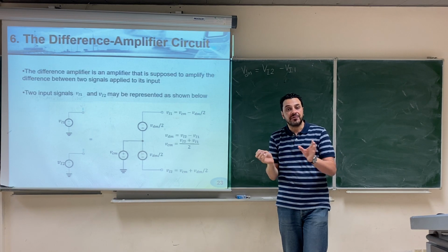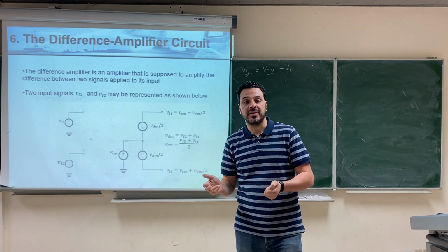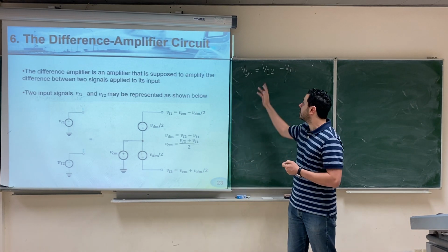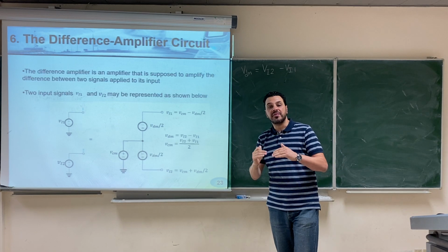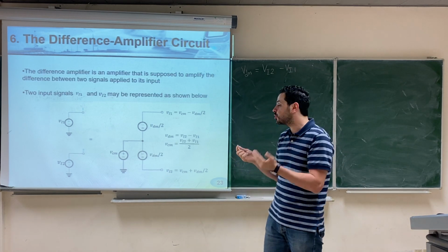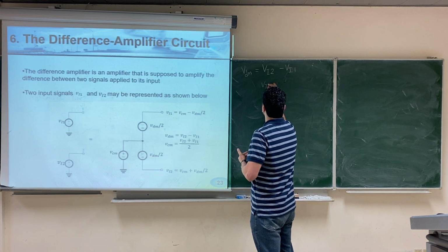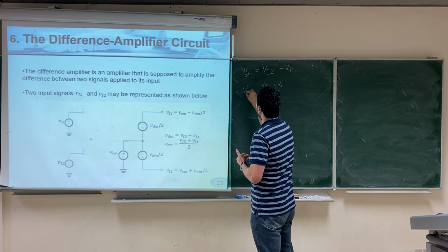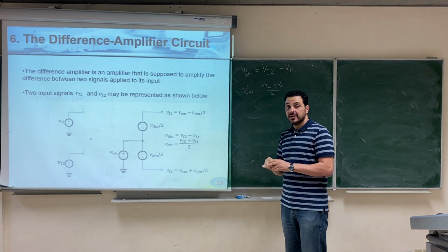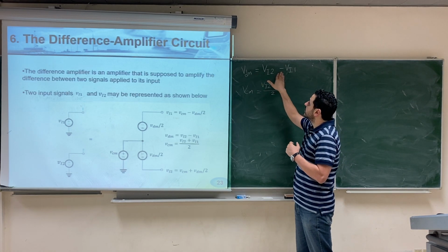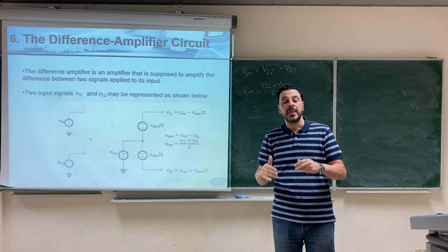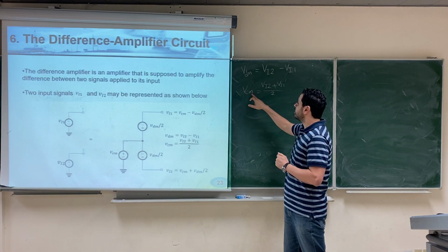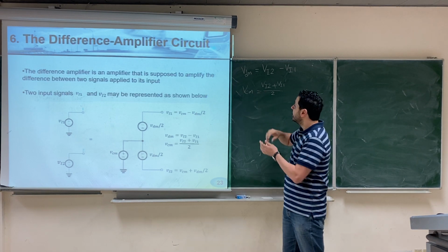However, they found that unfortunately the difference amplifiers that we design in practice usually do not amplify only the difference between the two sources. They also amplify the average value between the two sources, which is V input 2 plus V input 1 over 2, which we call V common mode. So we want to amplify the difference, but practically speaking, the difference amplifier doesn't only amplify the difference, it also amplifies the average, which we call V common mode.